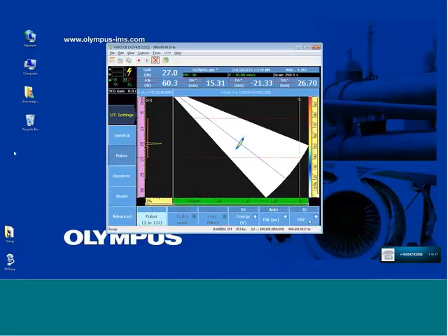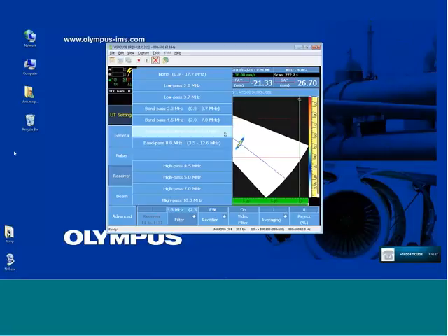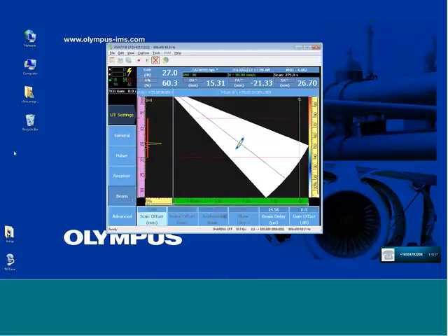Under our pulsar, we can normally just set it to optimum. Select one of 3 energies based on the pitch of the probe and best results. Select the filter. And our beam settings that you see here were generated by the phased array calculator.